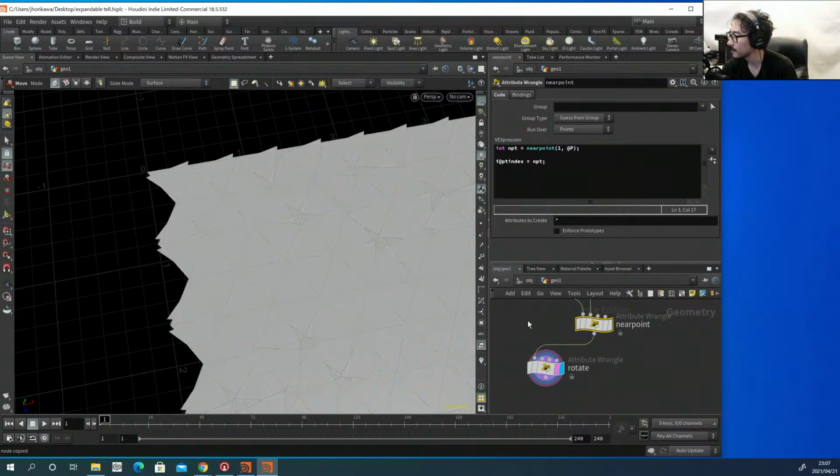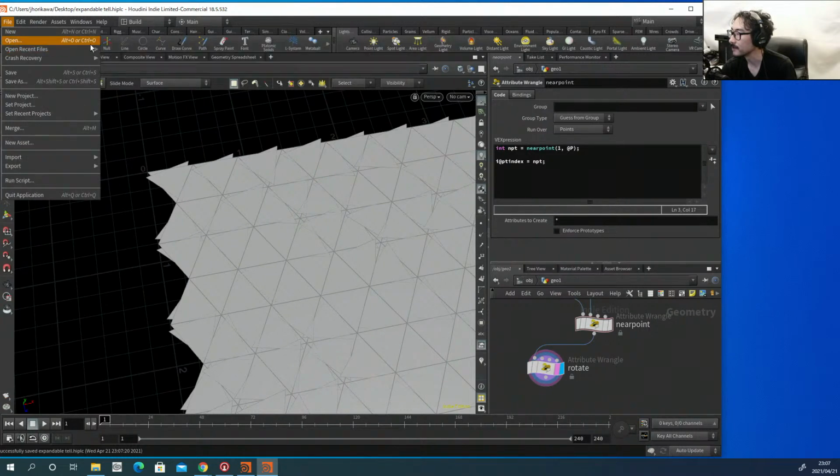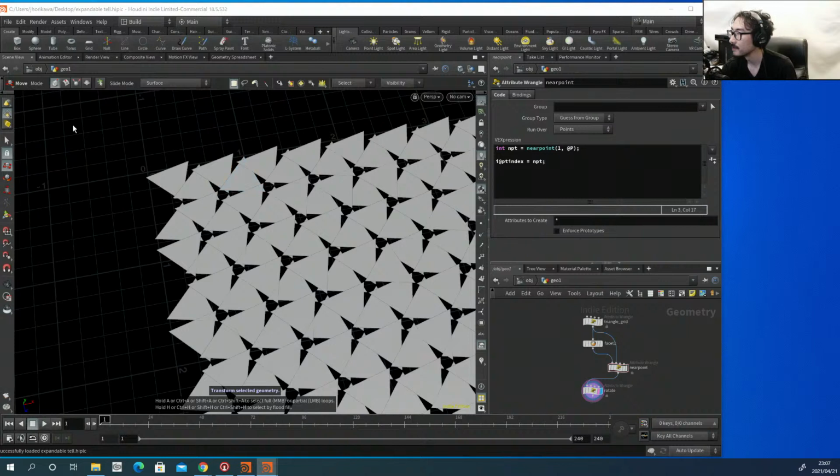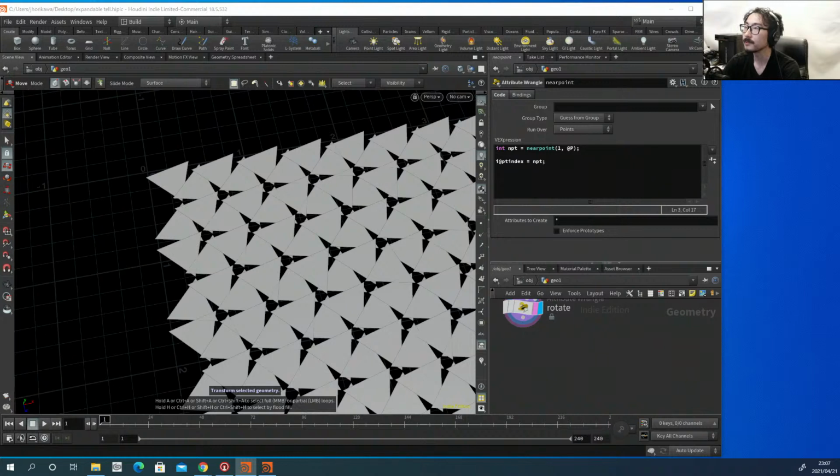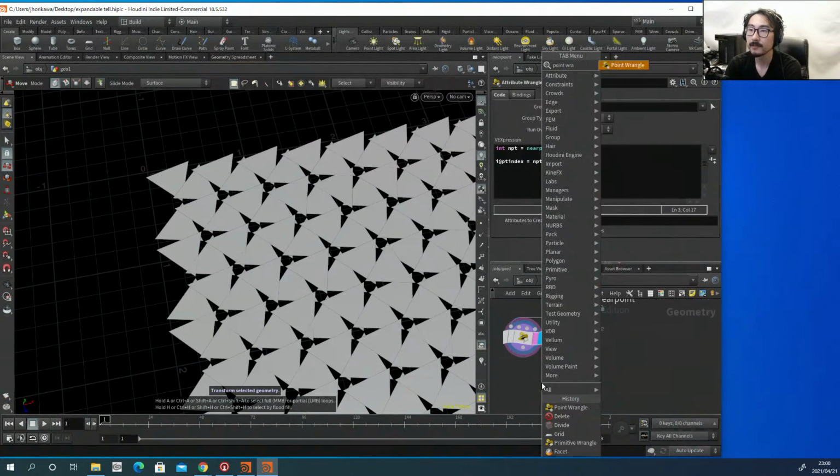Now's the time to offset the geometry so that I have the final parametric geometry, which is still phase 1. Okay, now let's see, this is a bit complex to do actually. Now how should we do this? I am going to use, let's say, a point wrangle in this case, and based on the i value or pt_index, create an offset. So let's do that. Point wrangle.